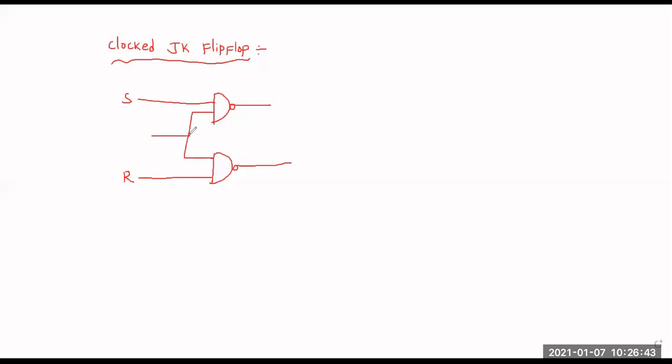That too, this is a positive level clock pulse. And after this, we will use the NAND latch, so we will have NAND gates cross coupled. The output is this one, and here the output is this one. So we are getting the outputs Q and Q prime. Clear? All of you clear, right? Yes, sir. So this is a normal SR flip-flop.